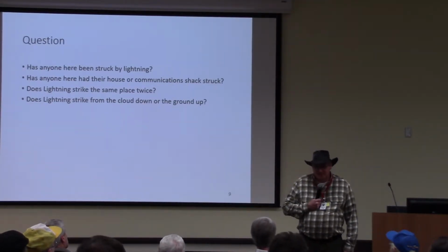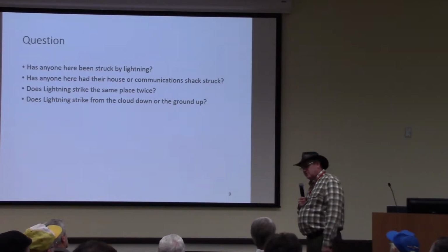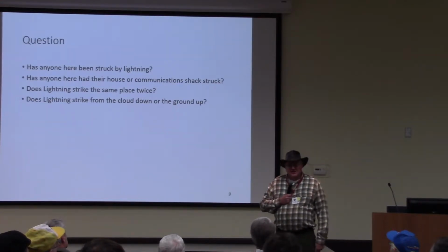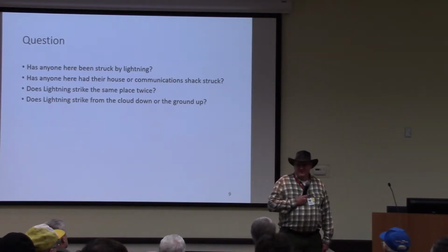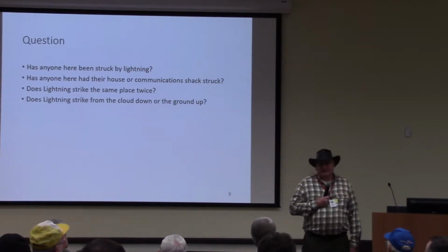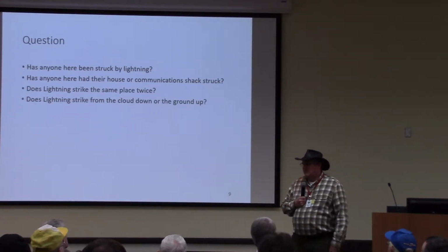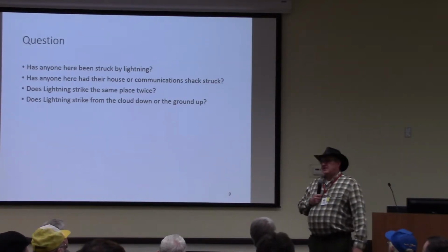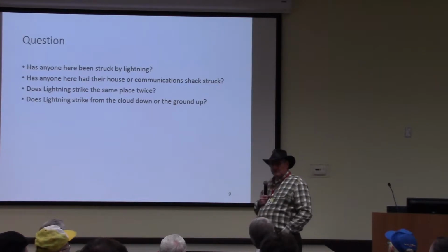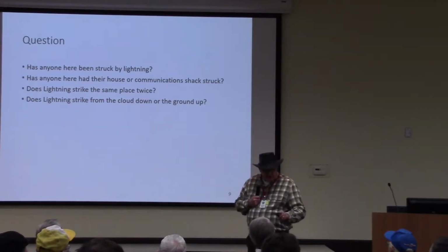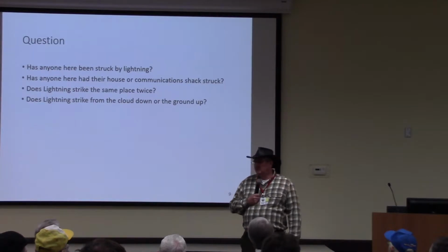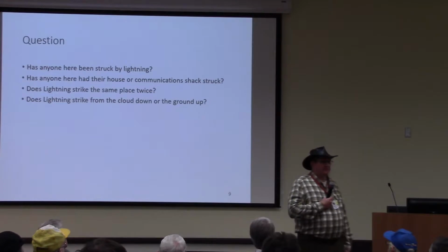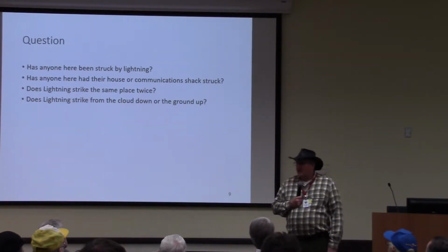The basic physics behind that little electrostatic discharge is, the basic concept is exactly the same as a lightning strike. The only difference is the intensity. You build up a certain amount of charge on your body. You're approaching another object that has an opposite charge because it collects. And then as you get closer and closer, it discharges. With the real severe ESD charges, you'll hear a zap and you can actually see the little arc. It's exactly like a lightning strike.